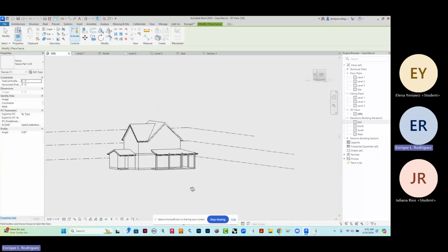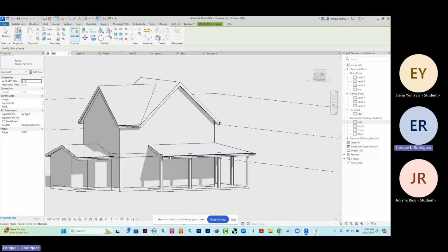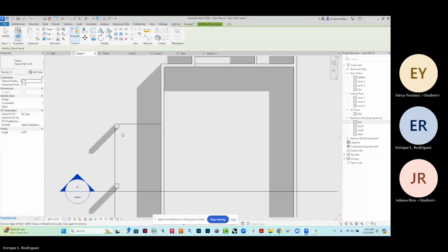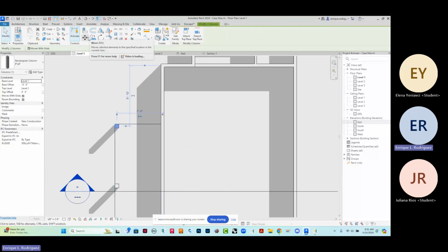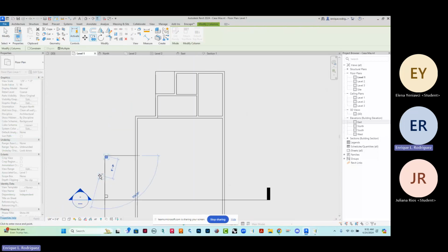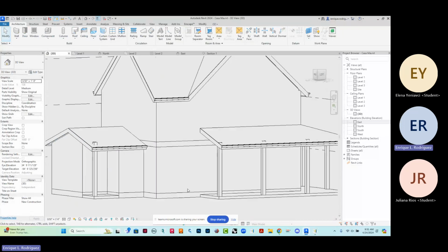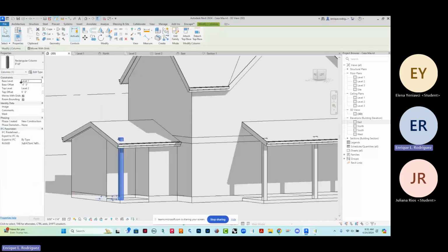What I'll be doing later on in the next video is probably creating the structural beams for support for the porch, which then can be translated over in here. This does need a column in the corner here. The simplest way to do that is go back to level 1, grab one of these columns, and then you can just copy it from that corner, place it up to that corner, go back to D, and that's what we've got there. Now these are pretty simple to change the levels and the base offsets, etc. So we can do that a little bit later on.